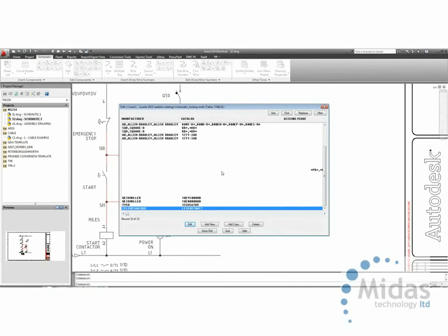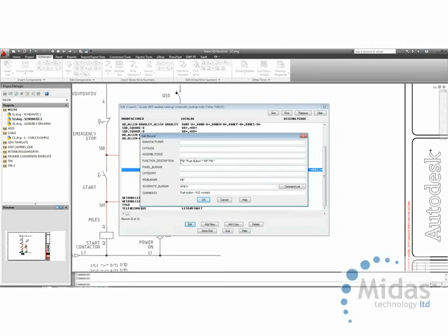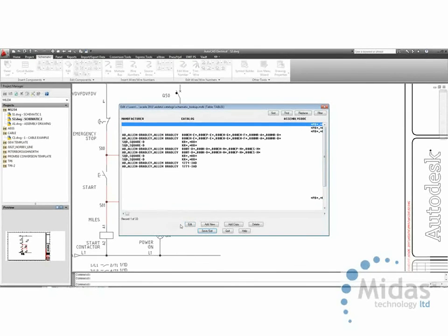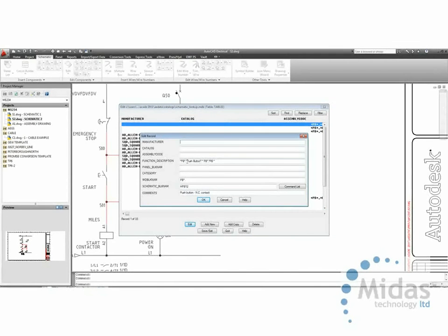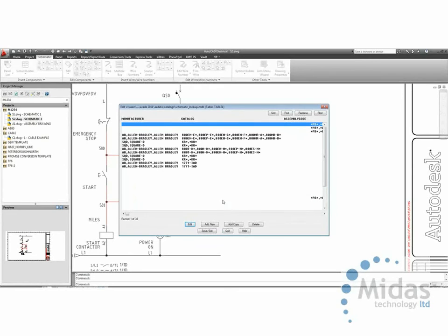What about if it was just a generic push button where you hadn't actually defined the manufacturer and part number, or the manufacturer and part didn't exist within AutoCAD Electrical but existed within the estimate? Well, what you can do is define anything with the word push button or PB in its title, and it will automatically pick up a block name called HPB11 or VPB11 as an example. Or anything with push button or PB might pick up HPB12. So in other words, all different potential options.